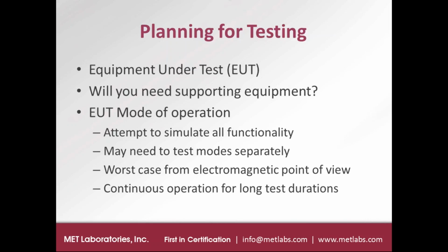You need to think about what supporting equipment you will need. During EMC testing, you need to establish a mode of operation. You should attempt to simulate all functionality of the EUT within one mode of operation, because that will allow you to run the tests one time each. However, if you have a complex device that can do a lot of separate functions, but it can't do them at the same time, then you may need to repeat each test more than one time. That's something you want to establish early in the design process, because it's going to drastically increase your budget for testing, both in time and cost, if you have to run test methods more than one time.